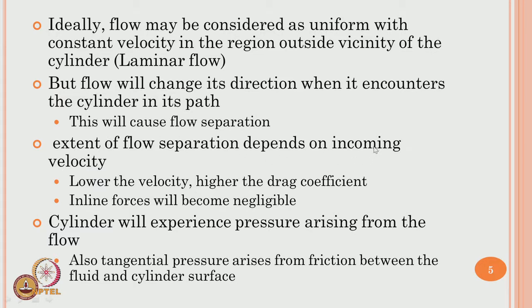One may ask me a question, what would be the influence of flow separation on the force exerted on the structure? Once the flow is separated, then they will act as independent medium, there is no interaction between the flow lines. So, the extent of flow separation depends on incoming velocity, lower the velocity, higher the drag coefficient.